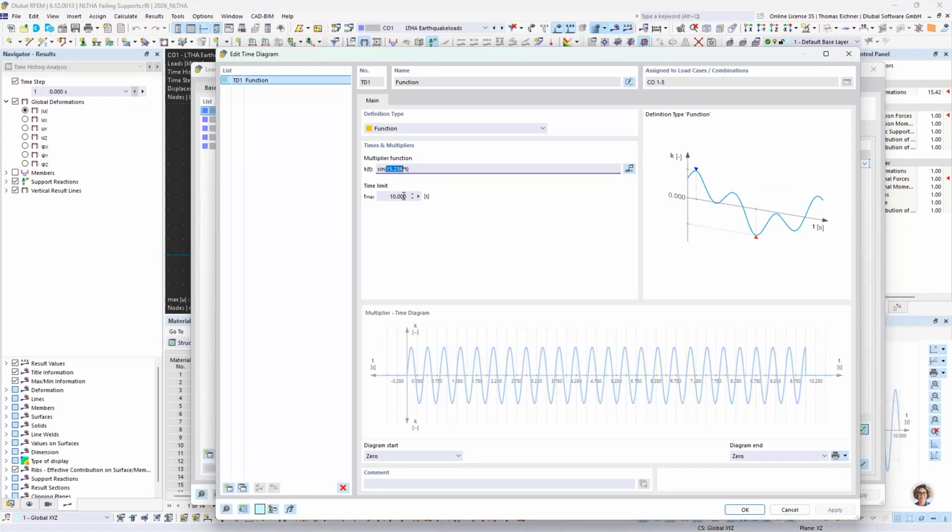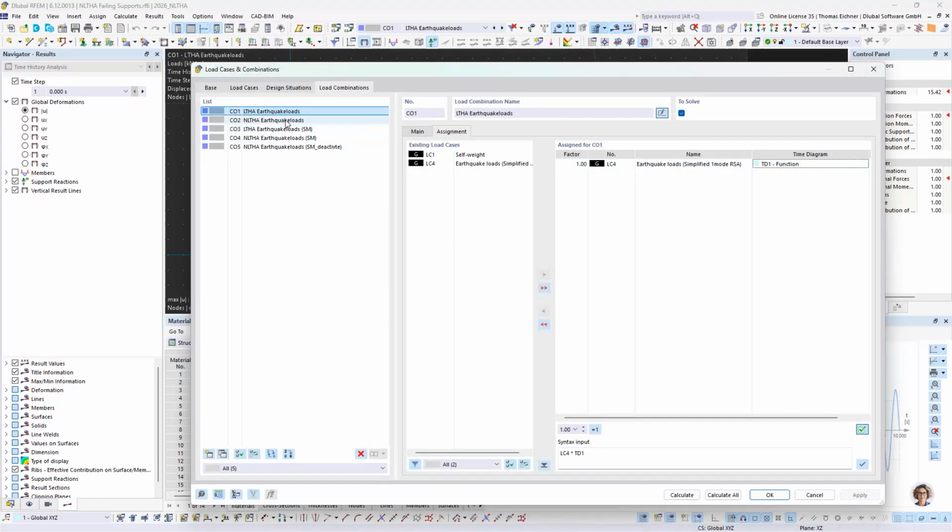It's the 15.236 rad per second. So it's not the natural frequency, it's the omega of the first mode of the linear system. I used it here and just applied the loading. I just applied the masses in x direction. That's what this time history does for linear and for nonlinear. So the same I did for the nonlinear time history analysis.